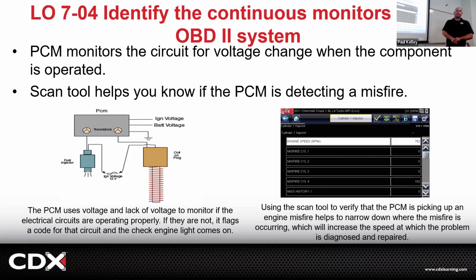Go ahead. If the fuel system is running too rich, could it also be the catalytic converter? No, it can't be, but potentially if it's running too rich, it could be a problem with the O2 sensor, but it could be like 10 other things too. So when we talk about the fuel system, that's a big thing we've got to cover. Fuel trim, I'd say, is one of the number one things people have a hard time understanding. So we're going to cover that in its whole day.